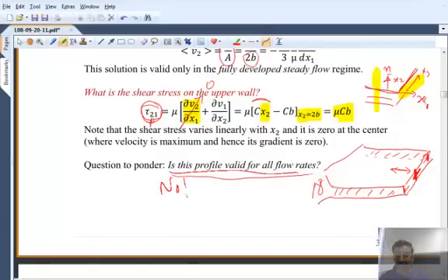What are the assumptions that I have placed? That it is steady flow, that it is fully developed, that it is one-dimensional. What happens is the flow becomes turbulent, and we will see what turbulence is later on. It becomes inherently time dependent, and all three velocity components will be non-zero. When that happens, we cannot solve this analytically. We have to go to the computers to be able to solve that, because the equations become highly nonlinear.